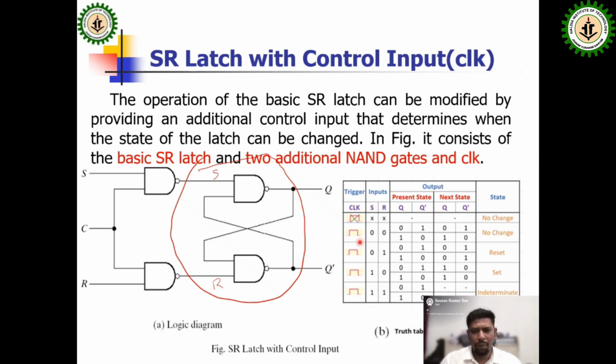When the clock pulse is applied and both S and R are 0, all possible outputs are considered. The present state is the value stored in the memory, and we don't know if it is 0 or 1, so both cases are considered: 0 0 0, 0 0 1 for the 0 0 case of the SR flip flop, then the 0 1 case, and the third case 1 0.